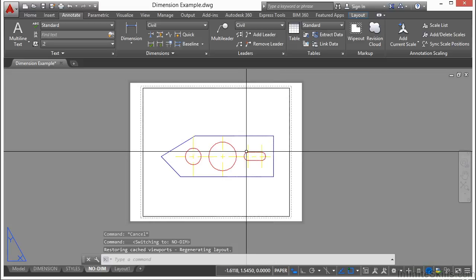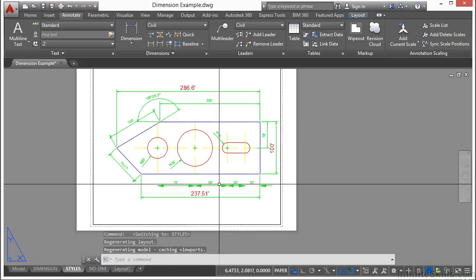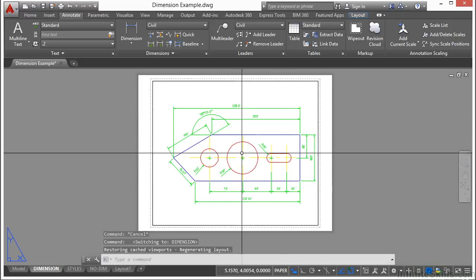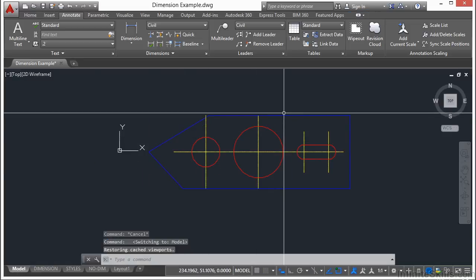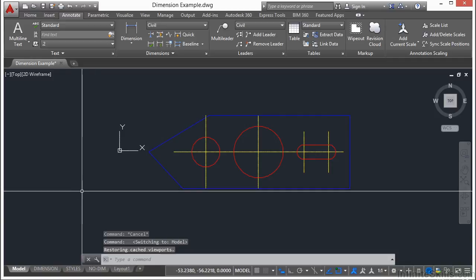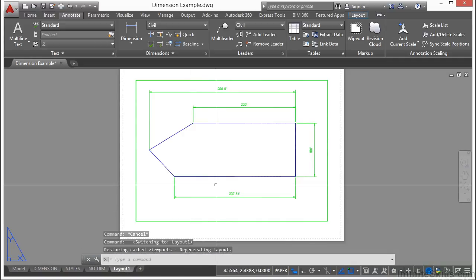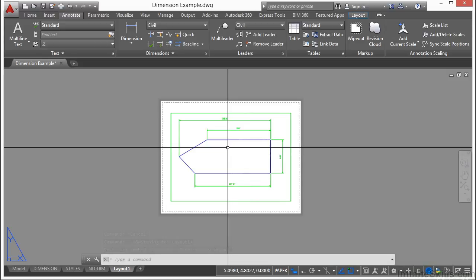This drawing of the same model has everything shown. This one has different styles of dimensions. And this one here is fully dimensioned out. If I go to model space, I have just my line work. So I created 4 different drawings from one file in one set of line work. That's the big difference between model space and paper space.